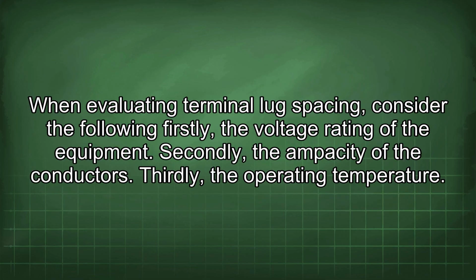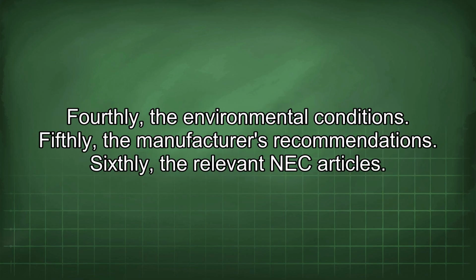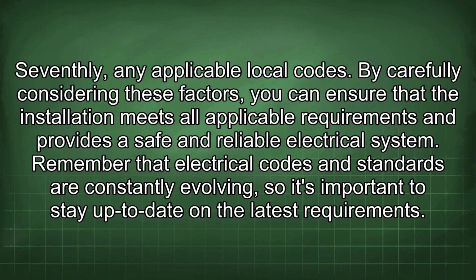When evaluating terminal lug spacing, consider the following. Firstly, the voltage rating of the equipment. Secondly, the ampacity of the conductors. Thirdly, the operating temperature. Fourthly, the environmental conditions. Fifthly, the manufacturer's recommendations. Sixthly, the relevant NEC articles. Seventhly, any applicable local codes. By carefully considering these factors, you can ensure that the installation meets all applicable requirements and provides a safe and reliable electrical system.